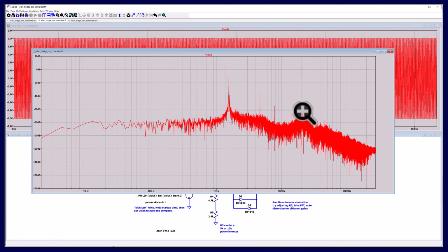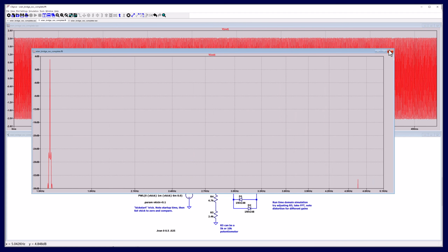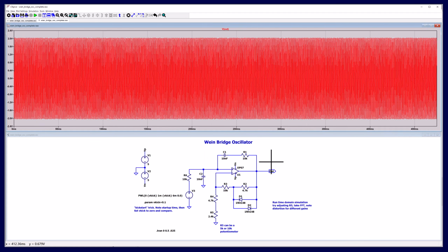We'll look at our first couple of components here. Again, if I start here, and a thing to notice, when I was clipping hard, the amplitude was about 10 dBV. Here I'm at about 3 dBV. So my overall amplitude has reduced, but that second harmonic distortion is now down 36 dB. So I'm approaching 1% distortion. Hey, look, I can start a big multi-billion-dollar company with my 1% distortion oscillator here.